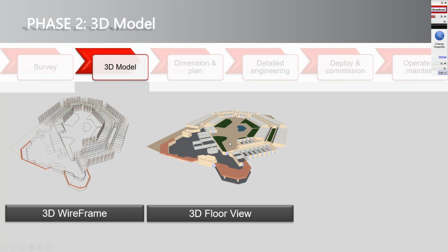And being able to visualize your floor in 3D gives you a second degree of confidence, because you can see all the different materials that you applied in different locations. And of course, if needed, at any time, you can right-click on any material, replace it, try a different material. And most importantly, from that survey data that we just collected, you can calibrate those materials. When we're assigning a material, sometimes we do a best guess, and we might not be 100% accurate on the attenuation, but running the calibration in iBwave really will adjust the attenuation factor to match the real data that you collect in the field.